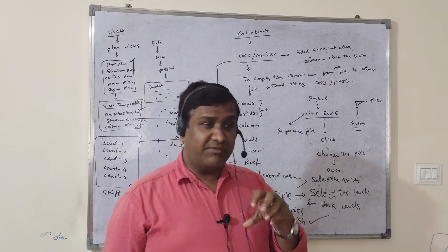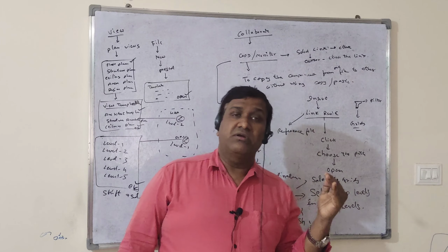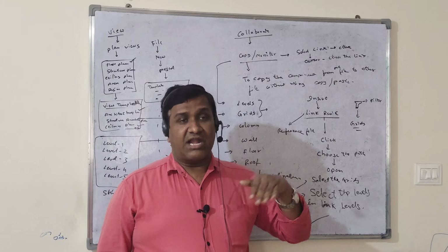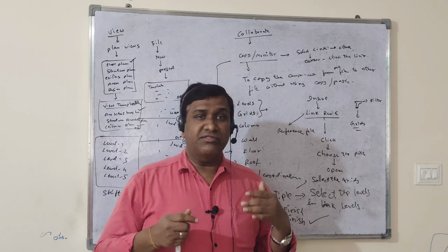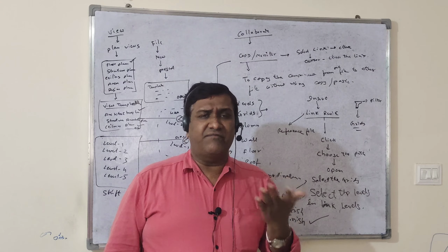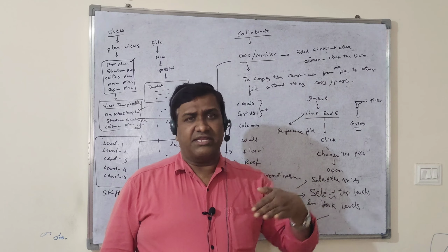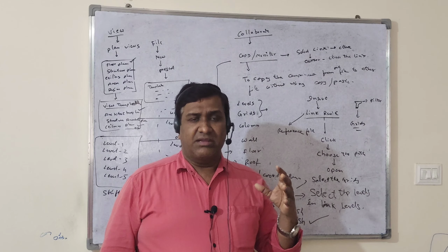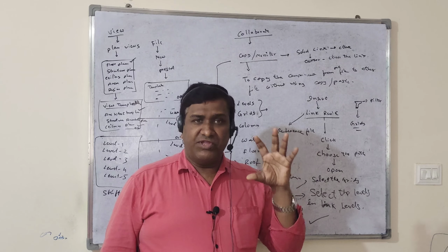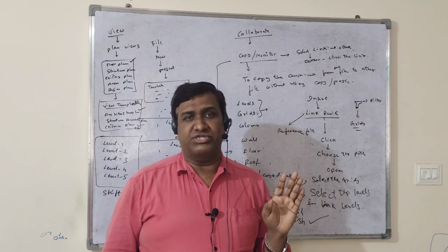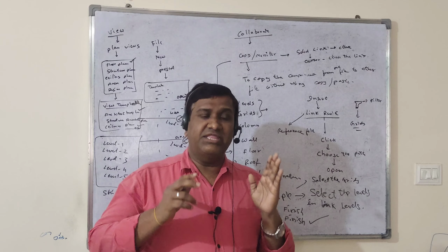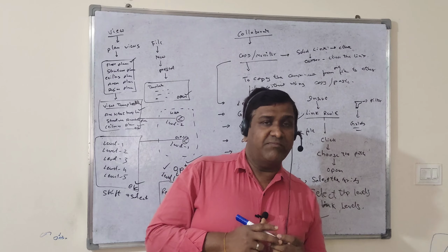Okay, but sometimes the MEP team will also start the project by creating their own levels and grids, because in their company they never wait for the architect's model. But actually the rule is that without the architecture model, the MEP team should not start any project, because the architecture is the only reference for the MEP people.